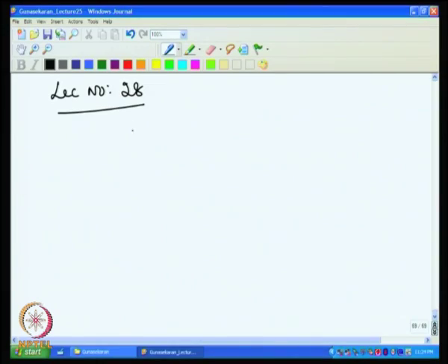Good morning. Today we discuss other issues of the operational amplifier, namely the impact of output resistance and how to find the output resistance for a given application, and then how to find the input resistance of the operational amplifier. These two issues we will see in this class. If possible, we will also see something more about CMRR and some examples to go with the input resistance and output resistance.